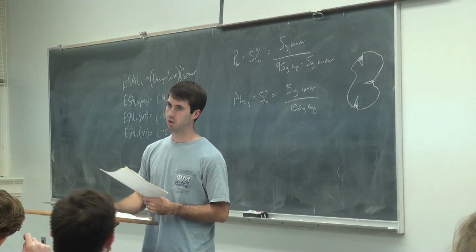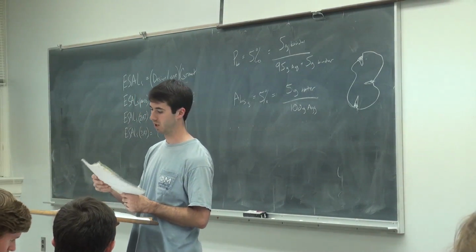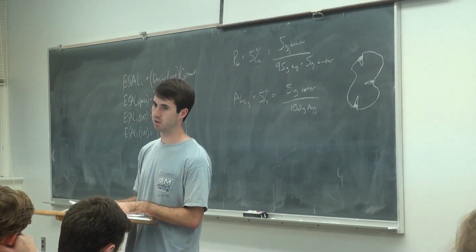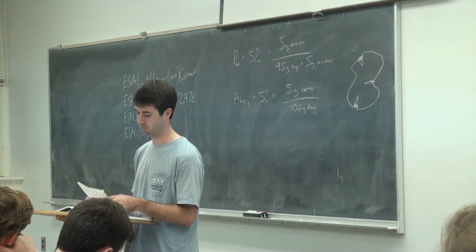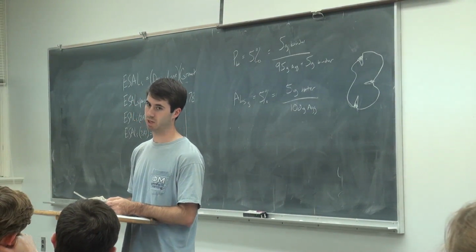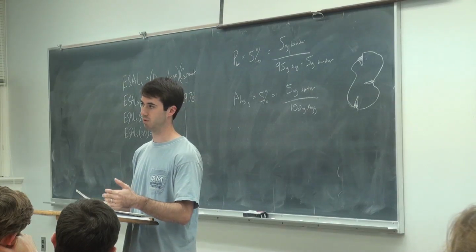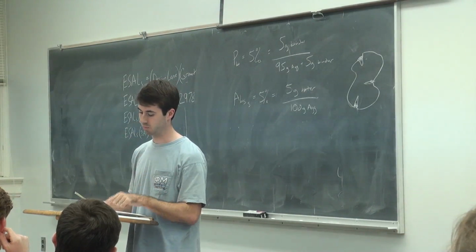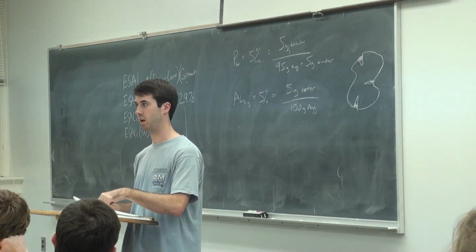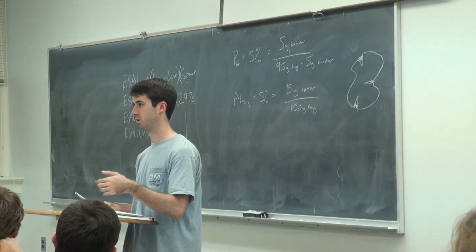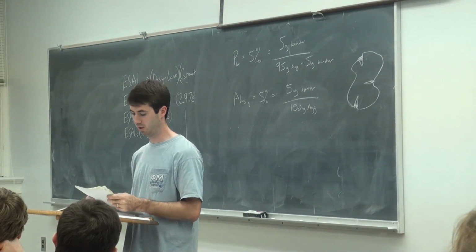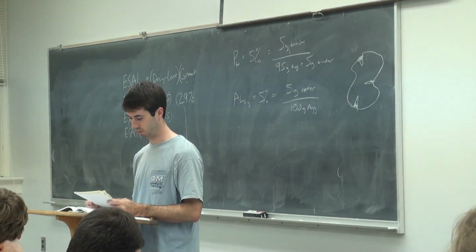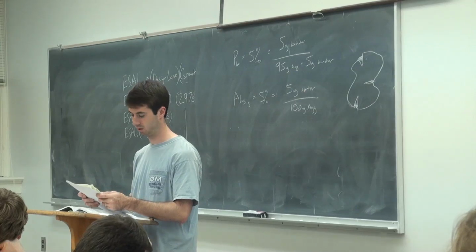So if you had 95% passing, 9.5 millimeter sieve, and then you go down to the number 4 sieve, and you had 89% passing, that means you had 11% retained on the number 4 or above. So you would take the number 4, you add 1 to it, you go back to the 9.5, that's your nominal max. Your max would be 1 more, 12.5. I don't remember what that person tried to tell me in the lab, but it's not that.